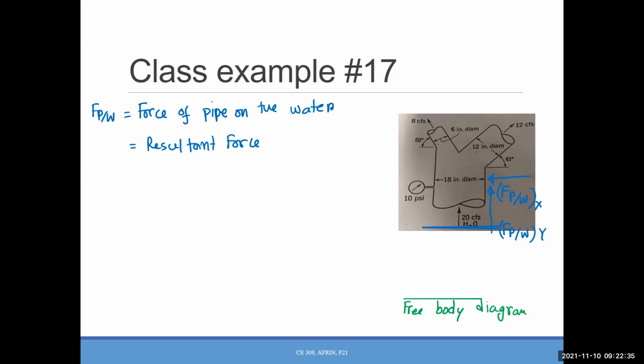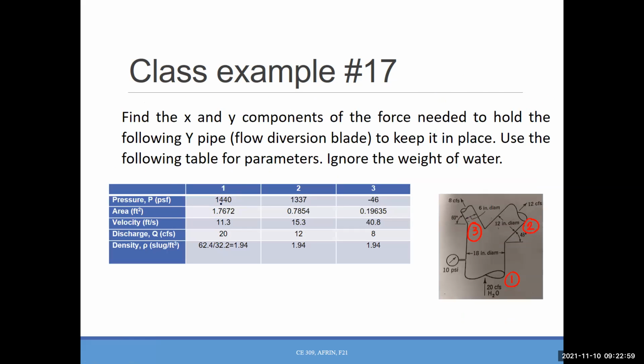That is one thing. Now the other type of force, what was the number 3 type of external force? We are done with number 1 and number 2. Number 3 is the pressure, right? In and out, that acts on open control surfaces. Now, if you go back to this table, we know the pressure at every point, right? But are you seeing there is a negative sign for 4 and 6 here and positive sign for 1 and 2? So what does that mean?